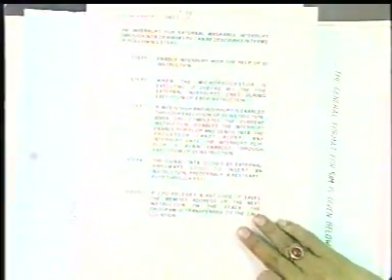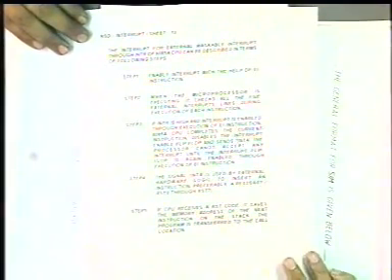Now, if I summarize the steps of what happens when an interrupt comes from an external line, which is INTR, the maskable interrupt: the first step is you have to enable the interrupt by an enable interrupt instruction.